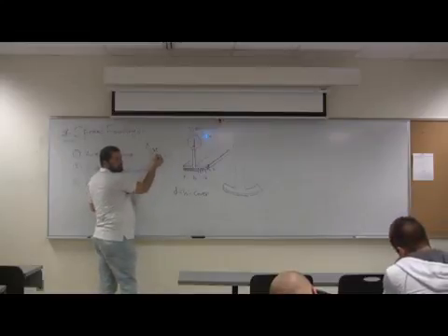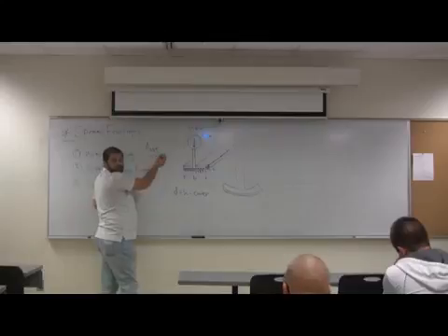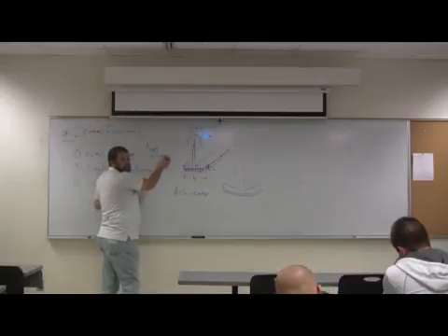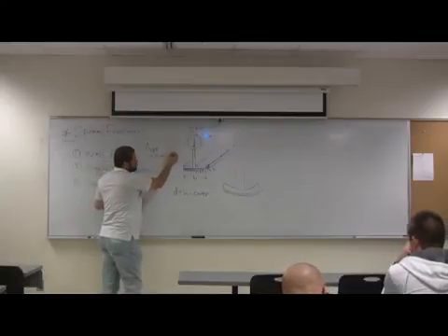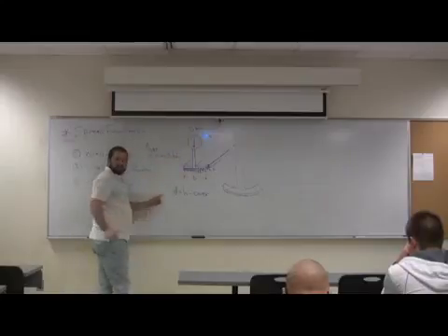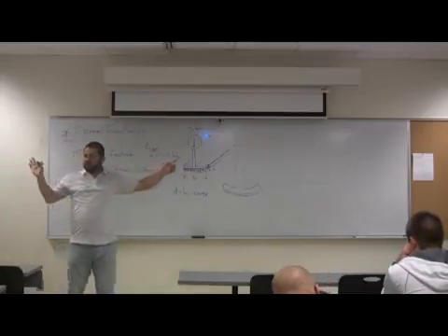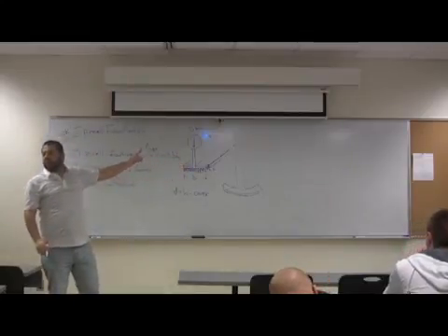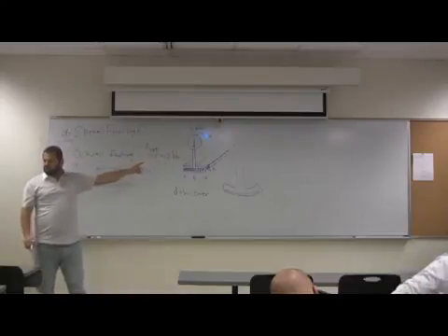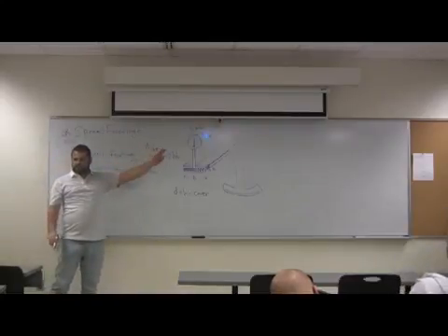In slabs, how much was it? 0.0018, right? Here it's 0.002 bh. Over there we multiplied by bh, but it was 0.0018. Now it's 0.002. That's in the wrong direction.